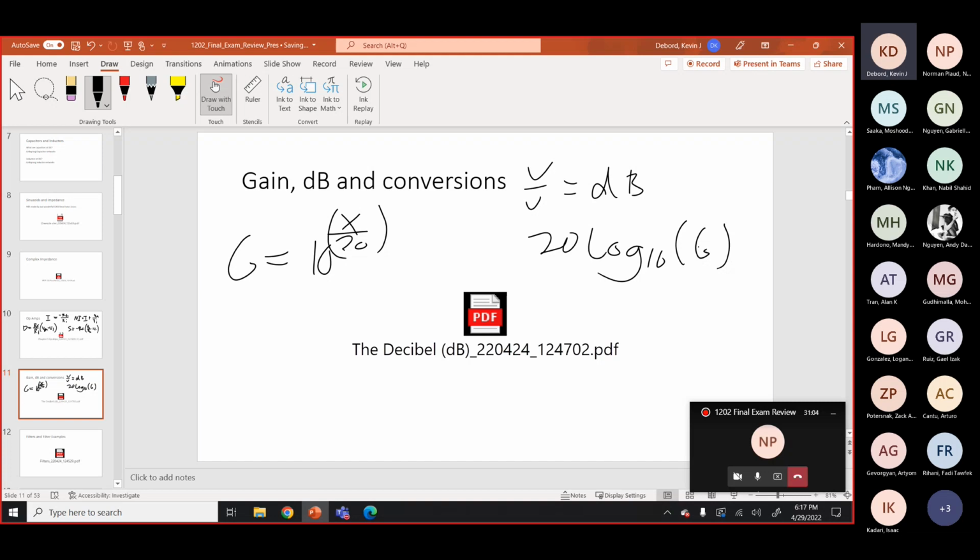Okay, so half power point. How would we find the half power point, let's do it both ways actually. The half power point in gain and the half power point in decibels. So that means at the cutoff frequency. Minus 3. Yeah, so in decibels, to find the half power point, that would be decibels minus 3.